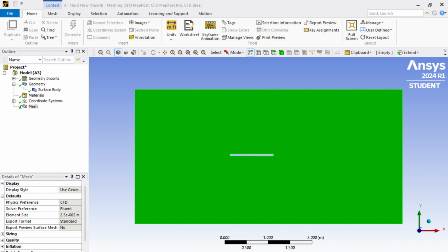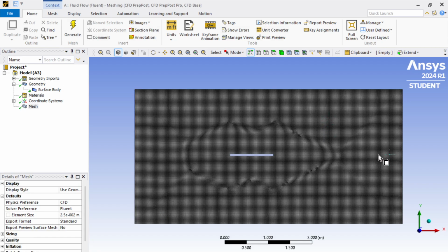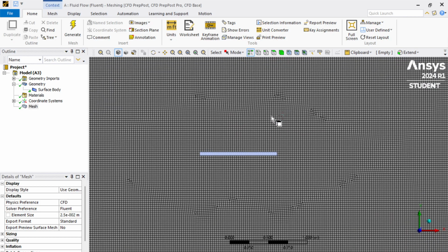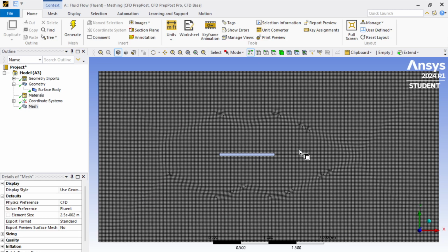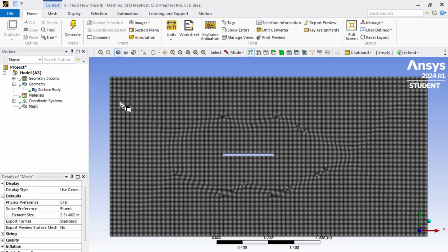You can see the meshing progress right here. It usually stays at 5% and then jumps to 100%, as you can see here. So these are the meshes. There are a couple of spots in this mesh which are problematic, like these spots. If you are an actual CFD engineer or computational engineer, you want to take care of these spots, but for the purpose of this lab, we don't really care about this.